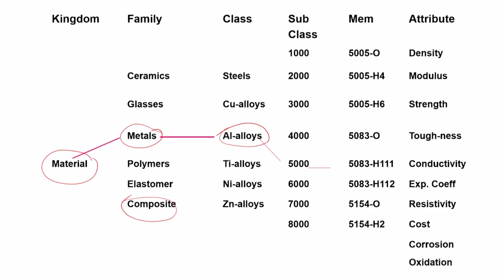Now, as I just now told you, aluminum has all these varieties in it. The variety that we will go for is the 5000 variety. Why? Because it is the 5000 variety which can be used in terms of a thinner skin and also is better in terms of corrosion properties, and it has good strength.